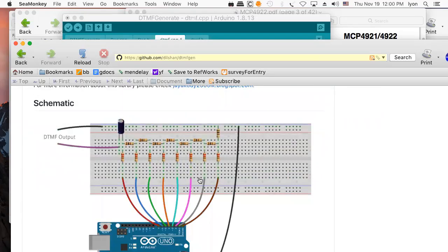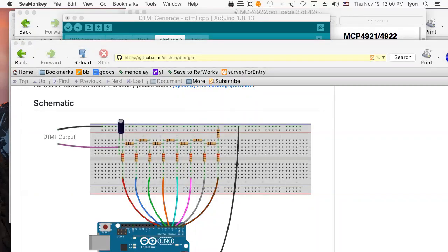And that's a way to make a DAC. I mean, might even be a good way if it's good enough for you and your application. And all the resistors are the same here, and they're all the same up in there, except this one doubled. And other than that, there's a little cap, and that's your DAC. And it takes up like 8 positions worth of output. And so he's writing to positions 0, 1, 2, 3, 4, 5, 6, and 7, which, I guess that's okay. You can do that.